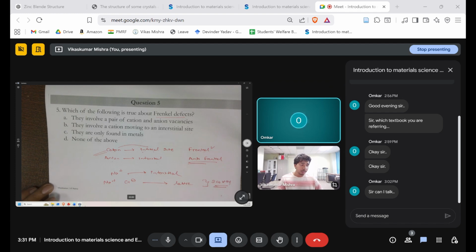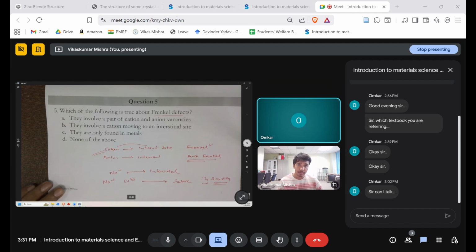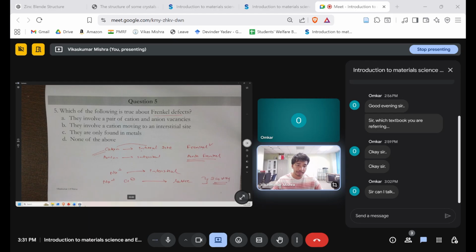Okay. Sir, one more thing: in Schottky defect, it is leaving, right? Not to the interstitial position, right? Interstitial space, yeah. We can consider that it can even go to the grain boundaries also. So a grain boundary can act as an additional surface, and the surface we can also consider as an additional surface. So if both of them are leaving the lattice together and going to a certain defect, it can be the surface, it can be the grain boundary, then we'll call it the Schottky.